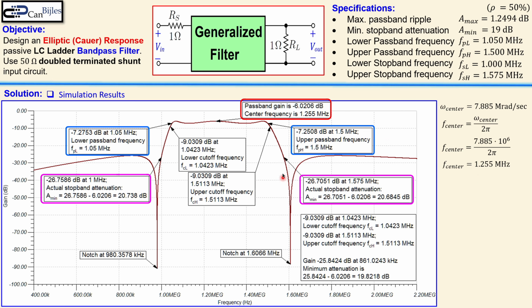What you also see, which is interesting, is that the gain goes up because of this notch again here, and it stays below some value, and that is 19.82 dB, which is what we have also seen in the table. So in the table it was displayed that the minimum attenuation you should get for these choices of the components is 19.82. So again, still higher than 19. So that is also fine. That means we have achieved our goal and designed this circuit according to specifications.